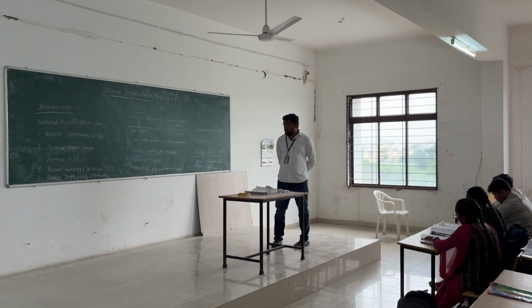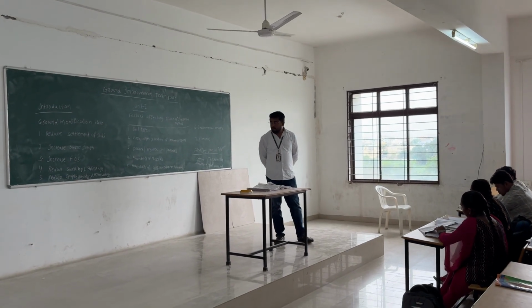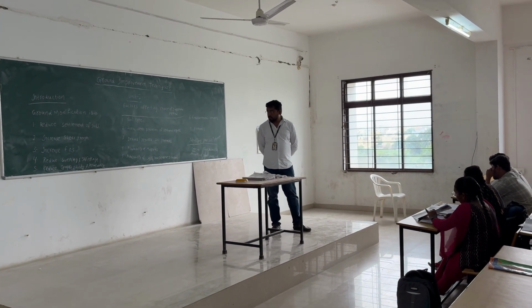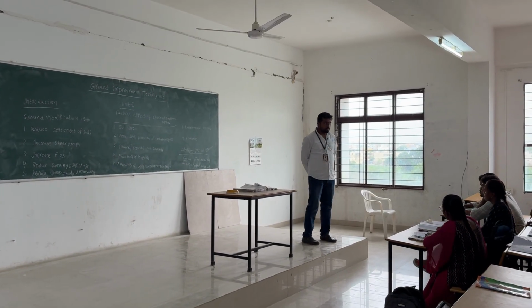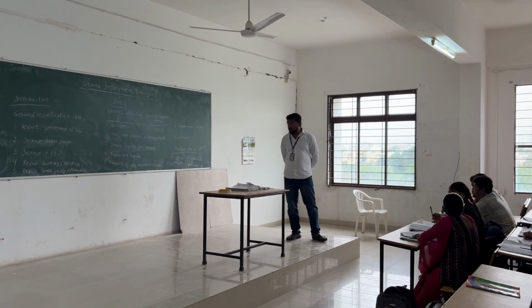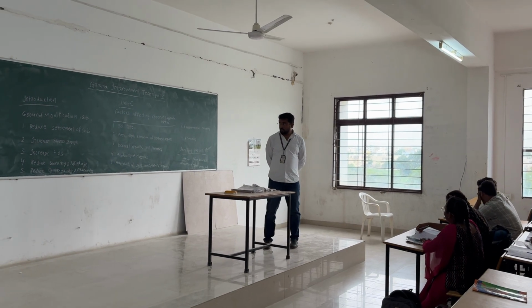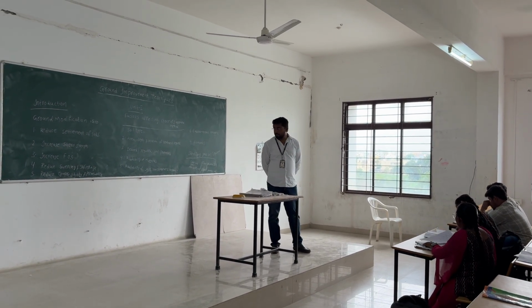Next one is to reduce swelling and shrinkage. How we reduce the settlement of soils by doing compaction, similarly, we can reduce the swelling and shrinkage by doing the compaction. We are going to do the compaction to remove air voids from the soil.